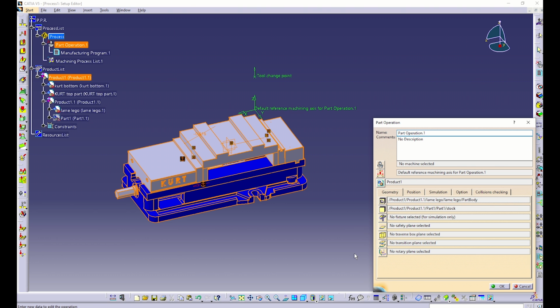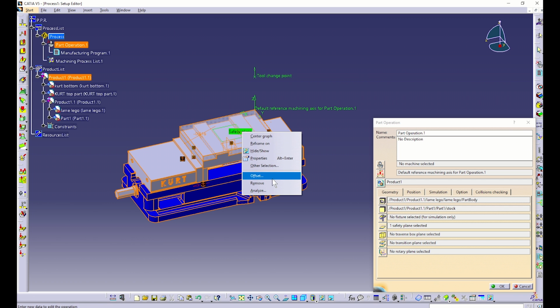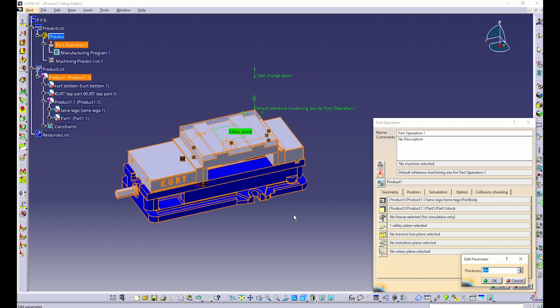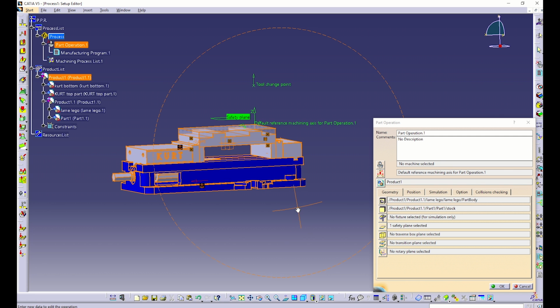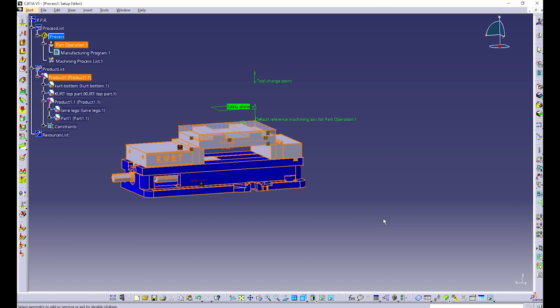Click the part. The different thing here, actually, we need to do our safety plane first. Just offset it because I didn't make a plane for that. A couple inches on top. The different thing here will be we're going to select a vise, which in the book gives you specific instructions on. Let's offset that a little more. If you click this guy right here, that's how you select the vise, which is what will show up in the analysis.